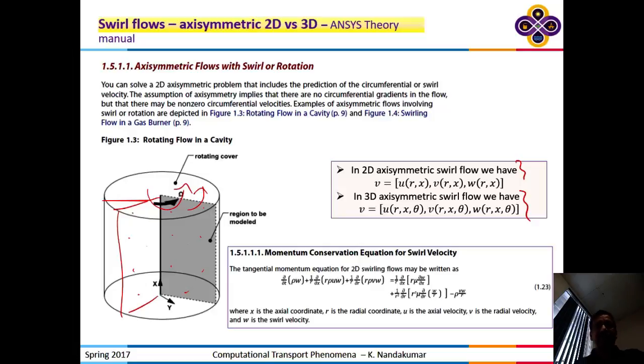What happens in some cases is the axisymmetry that is continuous, meaning the profile that you see at any plane should be the same. That's a continuous symmetry. Okay? That is broken, and you will see some sort of wavy vortices that are going around. So we say that the continuous symmetry is broken into a discrete symmetry in the angular direction. That is exactly what happens in the Taylor-Couette flow in the axial direction. Okay? If this is a channel, the one-dimensional flow is the same no matter where you sample. It just decreases, right? The profile is like that.